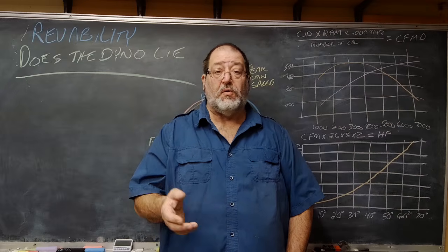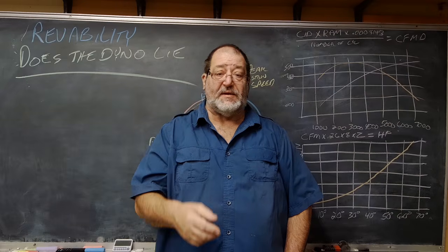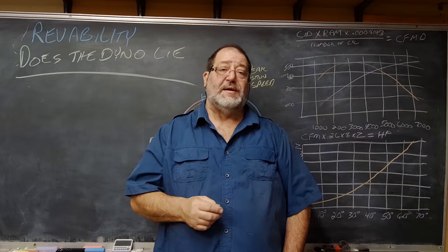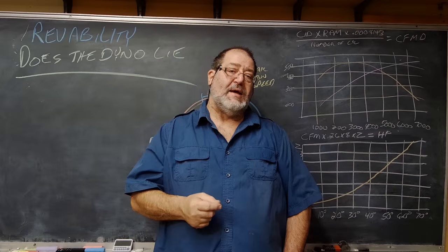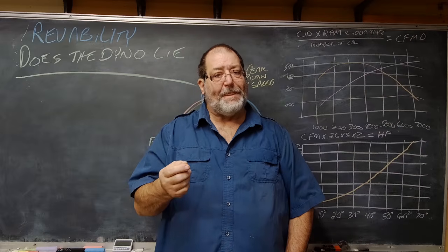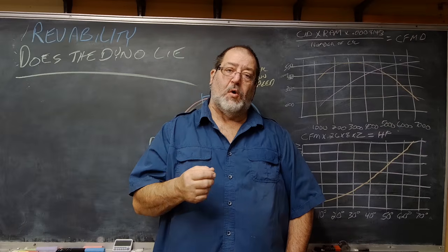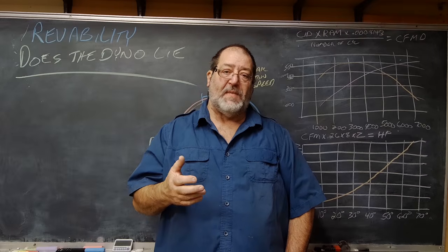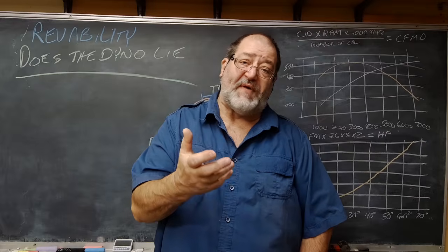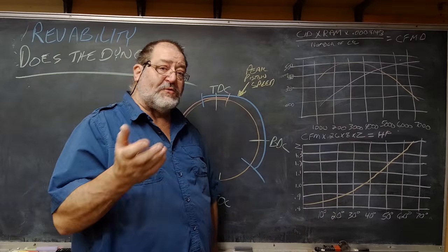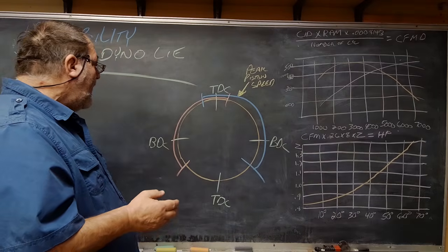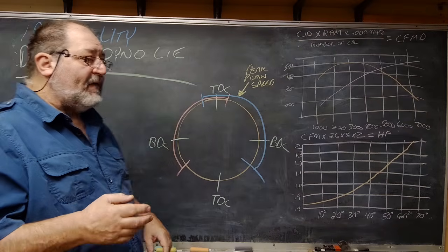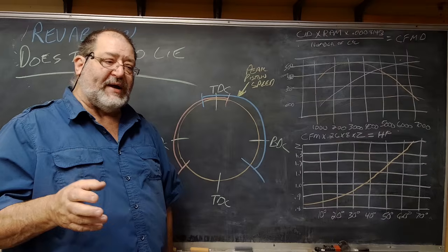Now on the dyno, that may have only been 15, maybe 20 horsepower. Not a huge difference. Yet when you're driving it, it feels way different. It seems to rev way better. And that's because you're affecting the breathing. And that's what I want to talk about today. The revability of a motor has a lot to do with how it breathes.